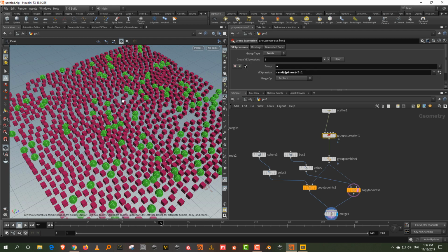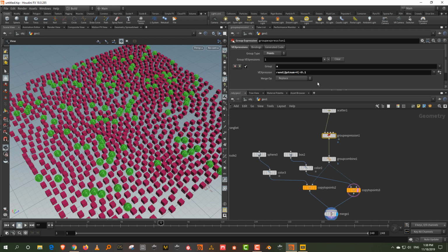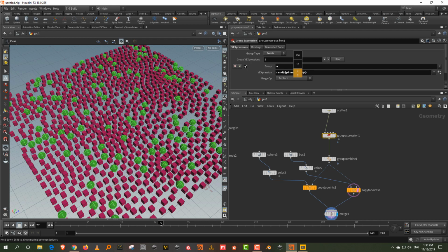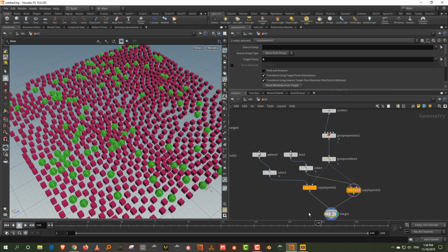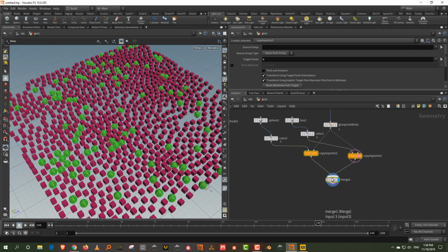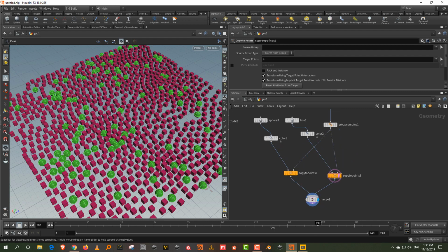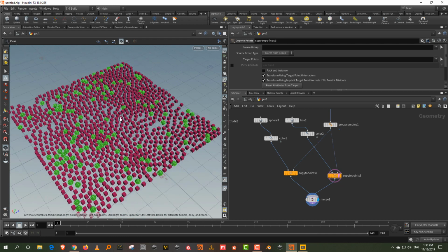And what if you want to change the selection? You just take the ptnum and add a value to it. That becomes like, if you're doing a math expression and you have an x in there, every time you change the value of x, you get a different result. So when you add something to ptnum, that becomes like an x. Whatever change I make over there, if I keep changing it, you'll keep getting a different result. So this is one way of doing this. This is how you can use the random function to select, or to make groups as well.